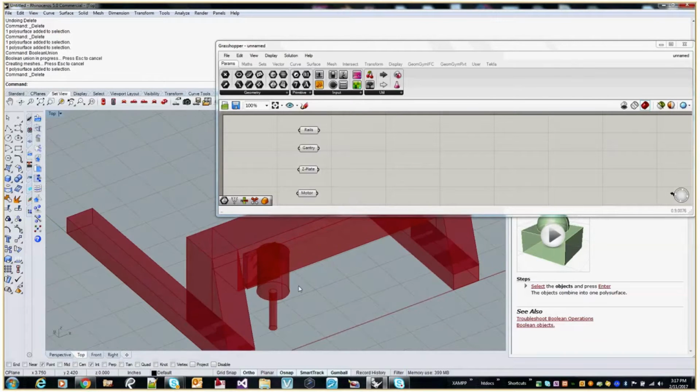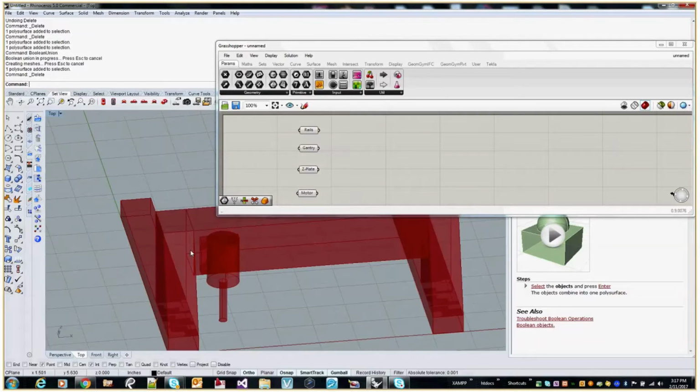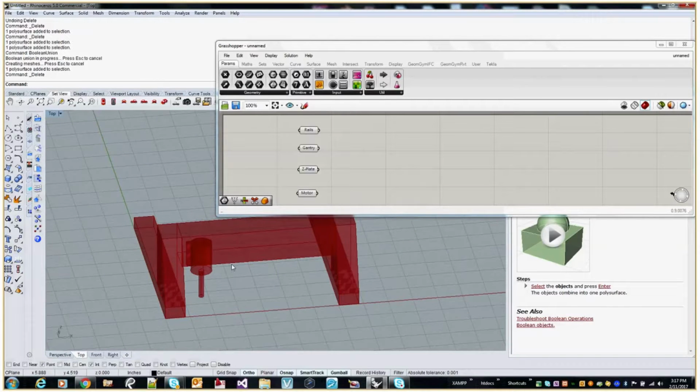It's going to have a limit on the lead screw or belt or whatever that's on. It's going to stop at a certain distance or hit a limit switch at a certain distance. So we just want to set the limits of all of these movements. And then when we have the limits of that, we work within those and everything will flow from there.